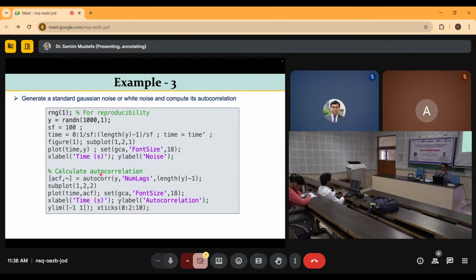Now you have to increase the efficiency of your algorithm. So how to increase the efficiency? You have to model the noise appropriately without any further inappropriate assumption. Suppose the noise is correlated, but you are assuming it is white noise. It is not perfect. It will give erroneous results. So you have to understand the true nature of the noise. Okay, so that is the idea.